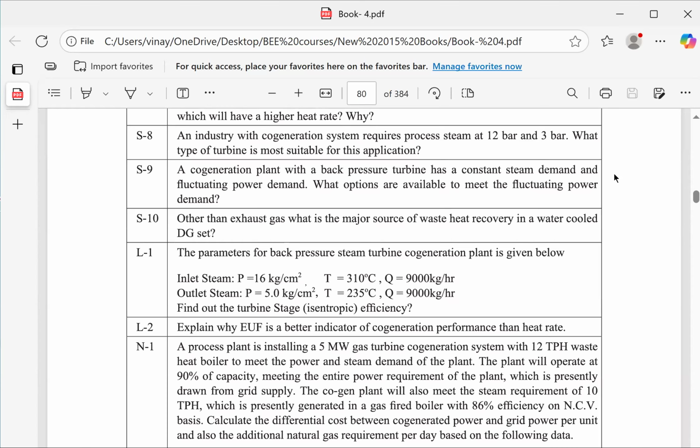So you should have a power purchase agreement with the grid. Whenever you need, you can buy the power from them. Nowadays, with the change in rules, the import-export meters installed at your factory end allow you to sell your power to the grid also. And the power purchase agreement will mention these clauses: purchase cost, sale cost, depending on metering, and at what time of the day you are purchasing or selling. Correct, sir.